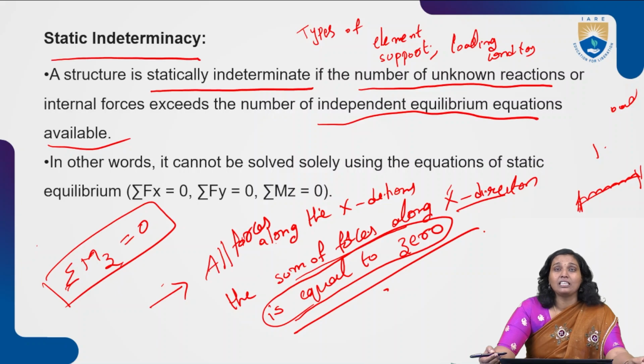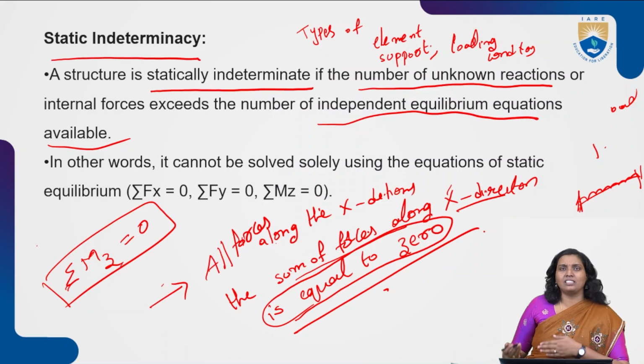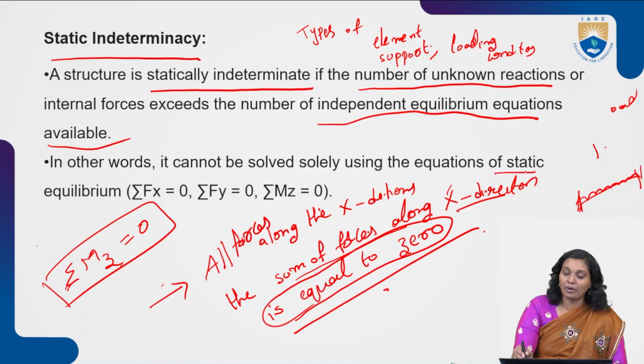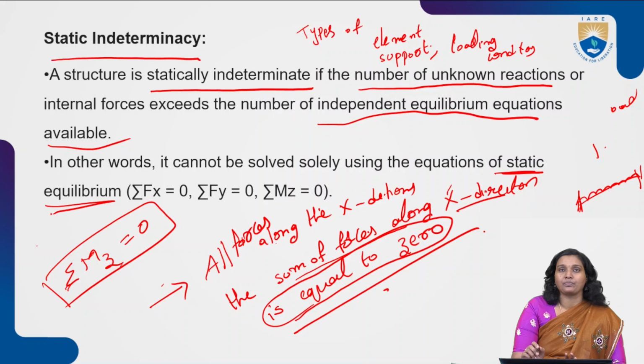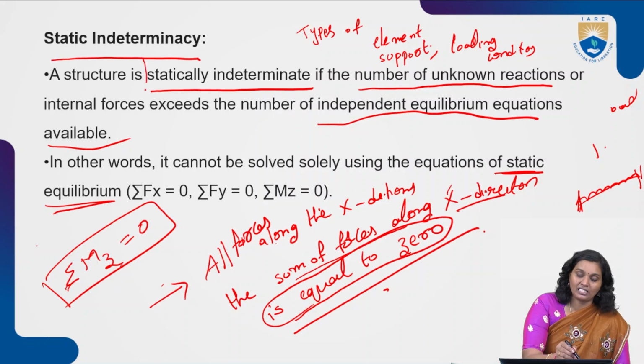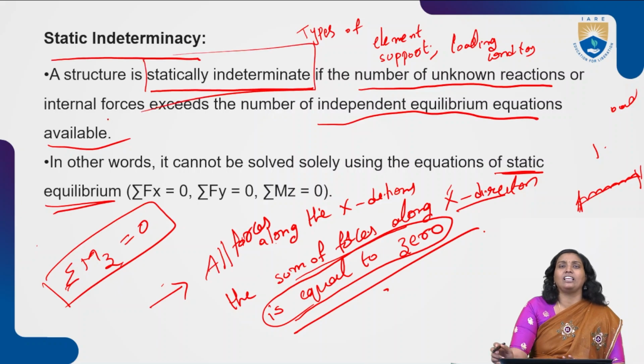In other words, it cannot be solved solely using these equations of static equilibrium. So these 3 equations are not enough to analyze the structure. Such a structure is known as a statically indeterminate structure.